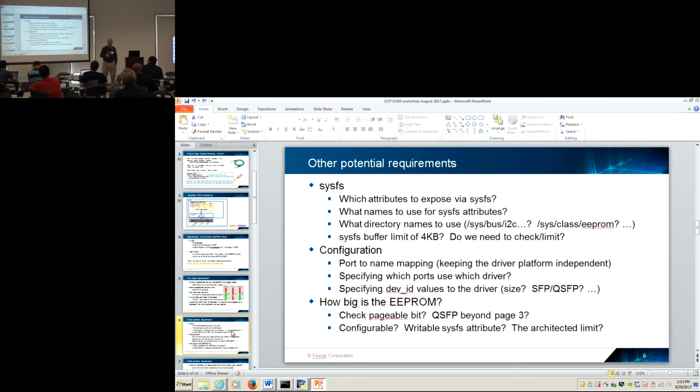I2C is as simple as the bus number you are on. And you said there's a fixed slave address. Yes. If you are on bus number 5, you will always be on that bus. Yes, but there's a parameter called dev ID, which gets passed when the driver probes the device. So the probe call says, here's the device, and here's a magic cookie that tells you about it. That magic cookie tells you things that only the driver knows what to expect, and they're coded up specially in the configuration process.